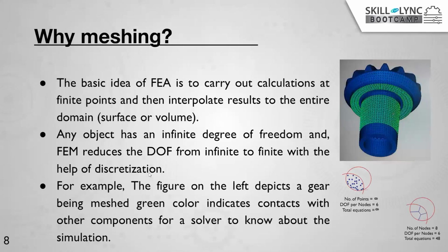Okay. Now, why do we need to carry out meshing? So first of all, any domain, any component which you are going to carry out analysis for would be having infinite degrees of freedom, because if someone asks you how many points are there in that component, it is infinite, right? You can't actually say a number for that. So in that case, if you are solving for infinite degrees of freedom, you might never be able to solve the analysis. Okay.